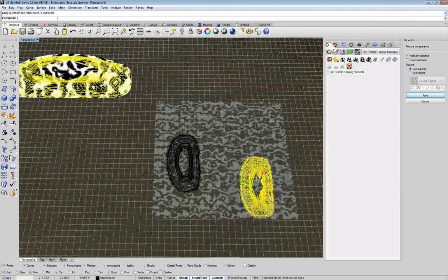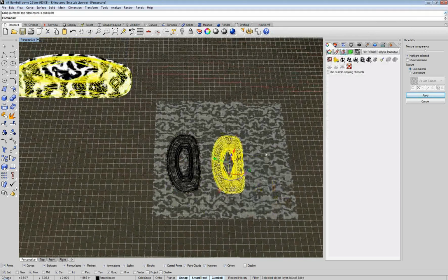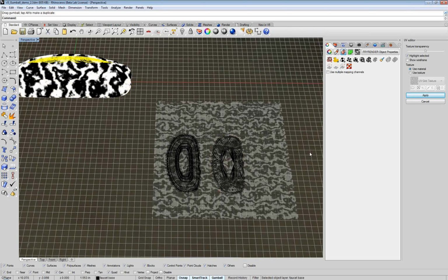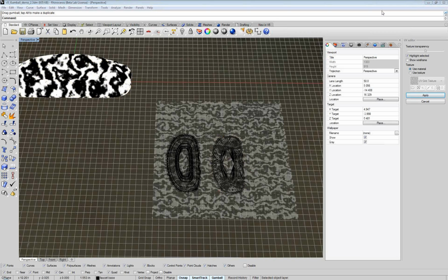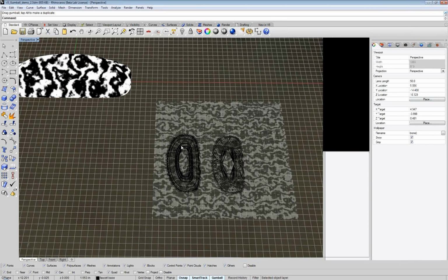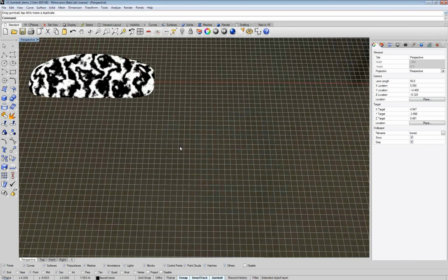This information will travel with 3DM files as part of the render mesh, but it also travels with, say, the OBJ file format when you check texture coordinate space as one of the attributes to transfer. And I'm still in the UV editor, so over on the right side of the screen I'll have to click Apply to keep those changes.